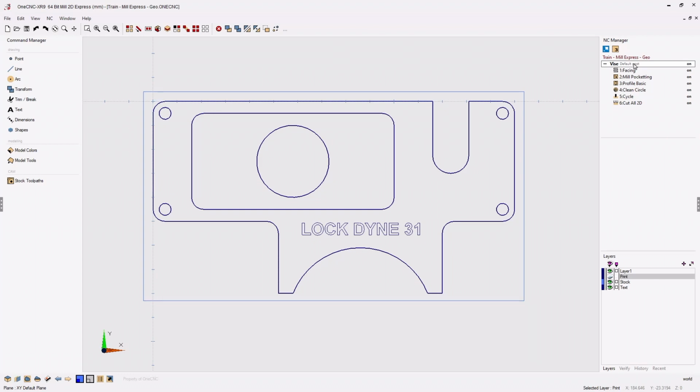Now, to complete the toolpath for this part, we need to take the part out of the vise and place it on a fixture plate, and then we'll perform the final profile operation. To accomplish this, we're going to need a separate toolpath group. The reason for this is simply that we want this extra toolpath group to be able to generate a separate CNC program, a separate setup sheet, and also use any post processor that we'd like.